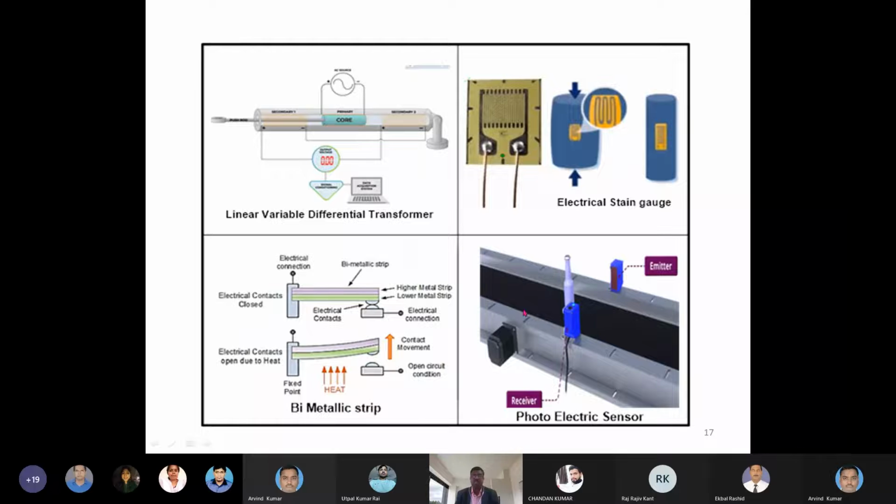This is the conveyor, and the object is coming on the conveyor. On one side we provide the photodiode, on the other side is an emitter, and when the light signal breaks due to the travel of the object on the conveyor, the emitter cuts off the signal. This information is sent to the controller to count how many times the signal breaks, and that many objects have traveled on the conveyor system. Thereby it is also used to count the number of components that the automated manufacturing system produces.